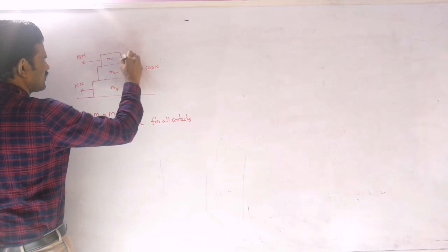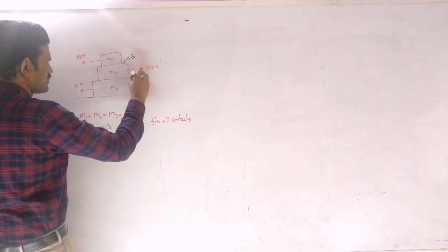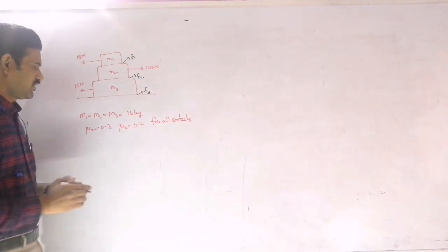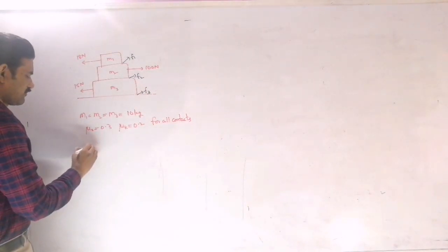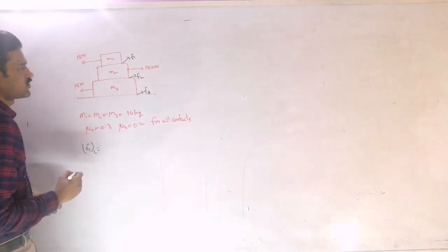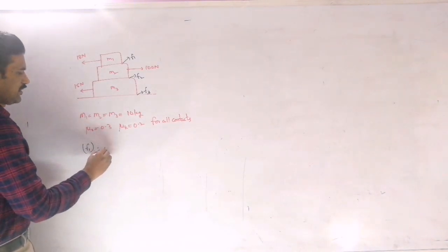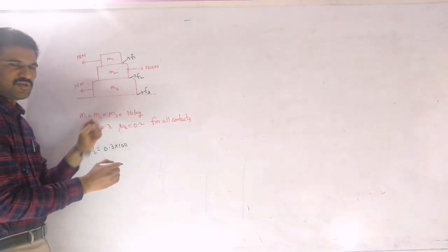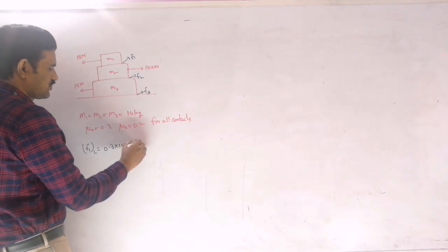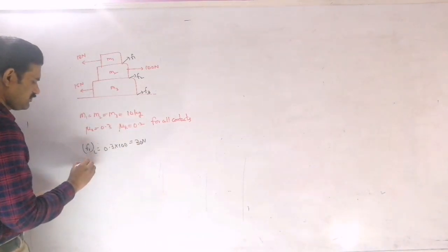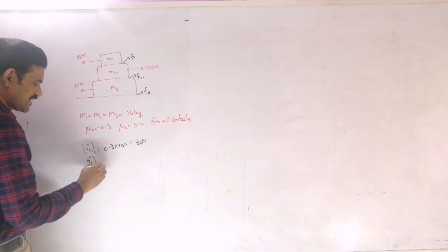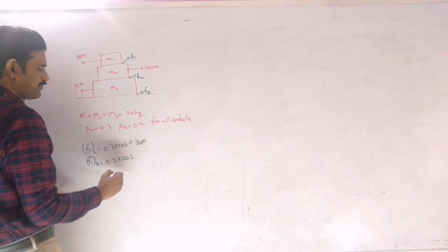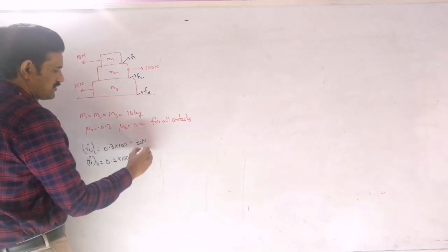Here I am taking this friction as F1, this is F2 and this is F3, right? So F1, F2, F3. Now I am writing F1 limiting. F1 limiting is 0.3 into 100, mg where m is 10 and g is also 10. So this is 30 newtons. Next, for the same surface, the kinetic friction we calculate here is 0.2 into 100, which is 20 newtons.